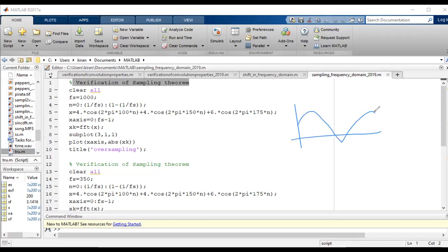say there is this particular wave which is analog. So the question comes in, you want to convert this to digital by taking a discrete number of samples. How many samples do you want to take per second? Are you happy with 100 samples per second, 1000 or 10,000? So it says that if you want to be able to reconstruct the original signal from its samples, your sampling frequency has to be greater than or equal to twice the maximum signal frequency.